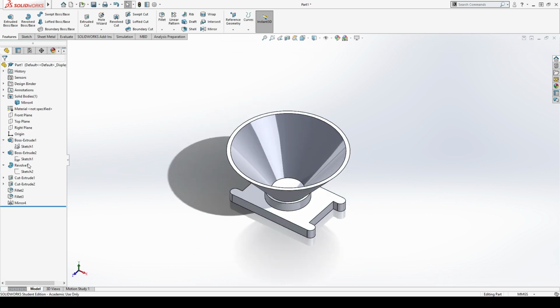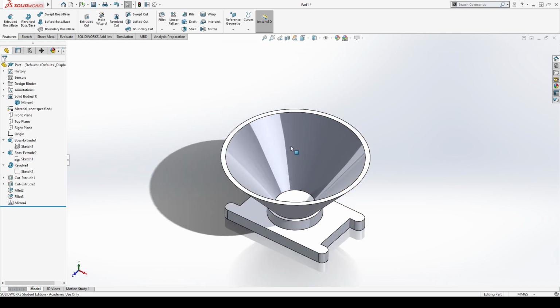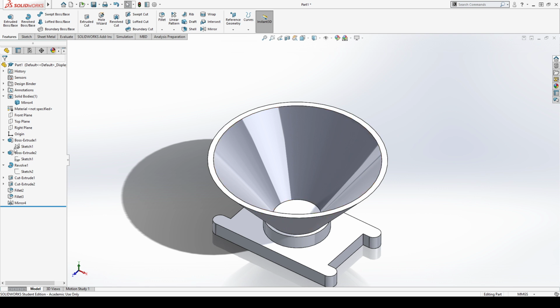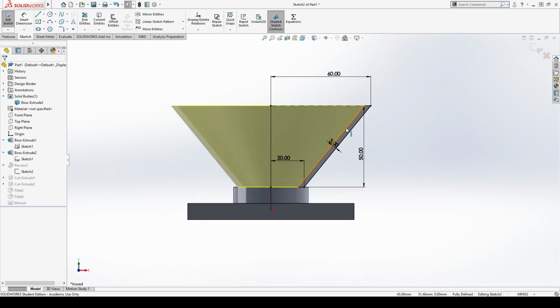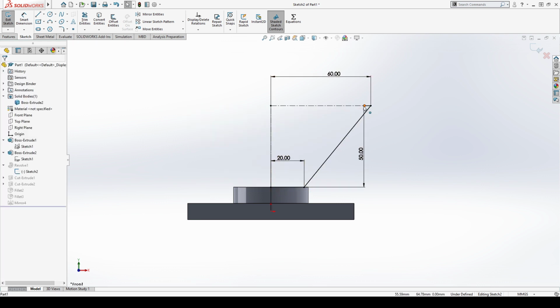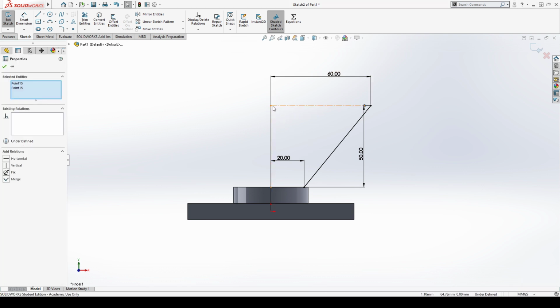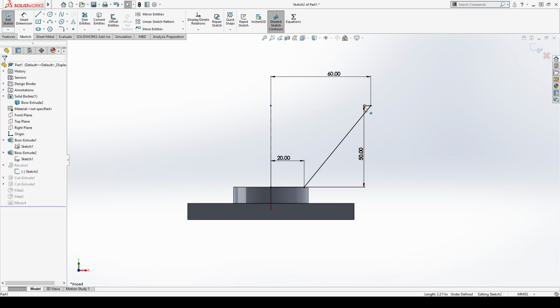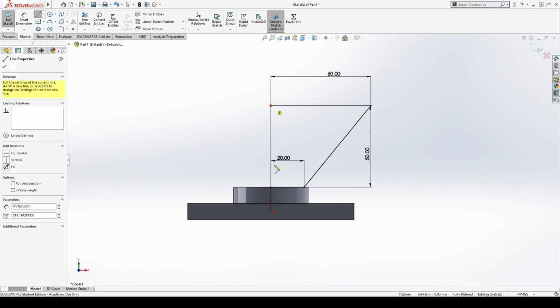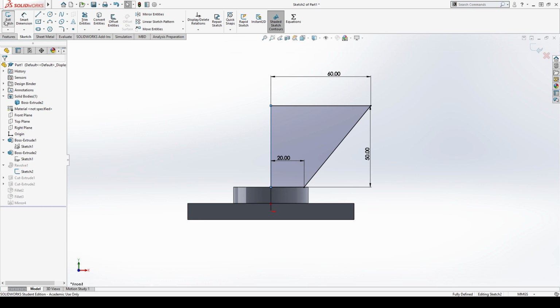If you remember when we had, let's actually go ahead and just really quickly fill in this cup here. So I'm going to go back to this revolve, edit the sketch. I don't want to do just the wall anymore. I'm going to go back to going all the way out. And go ahead and remove that construction line, move that out. So I do need to add in that solid line down the middle. There we go. Got my revolve now. Should be able to exit the sketch.